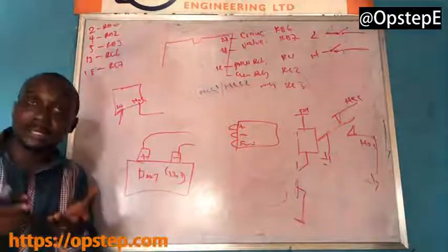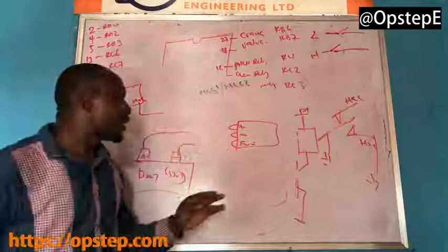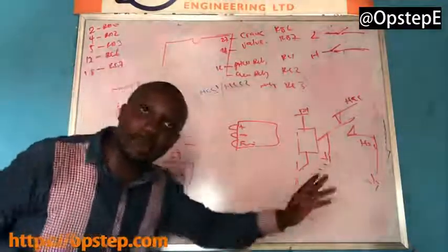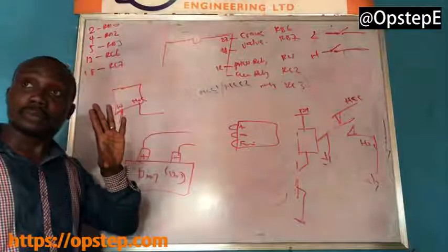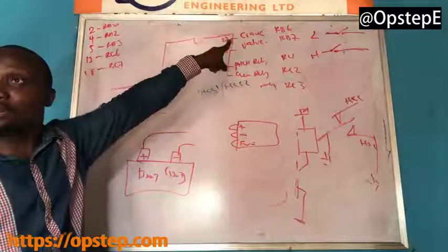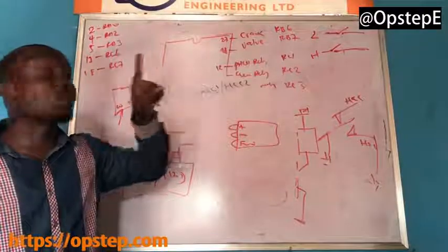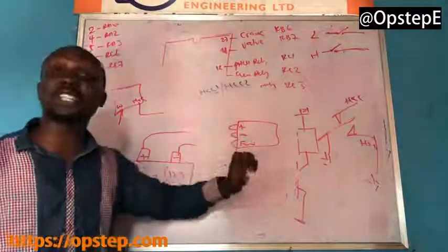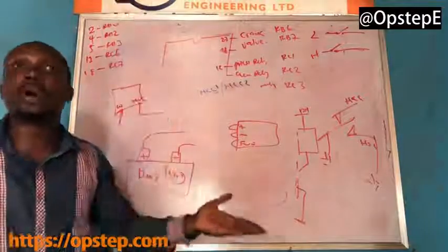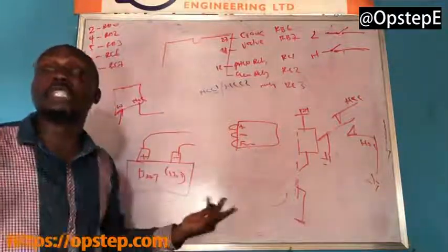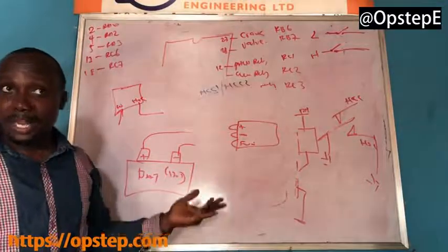But to understand, don't forget there are 2 different relays. The moment it starts, for about 3 or 4 seconds, you are supposed to stop the crank. But that valve must remain on. If the system tries to start and the generator does not start, that's when it goes and turns off the valve. But the valve should not be on if the generator is not running. We don't need fuel flowing into it if the generator is not running. Are you getting my point now?